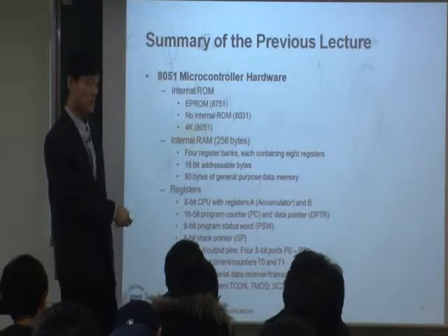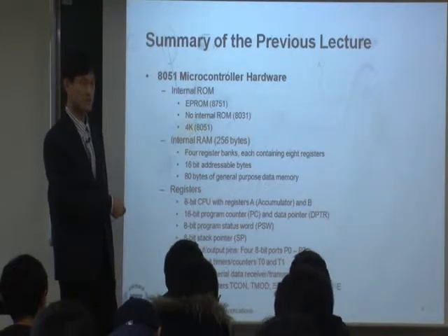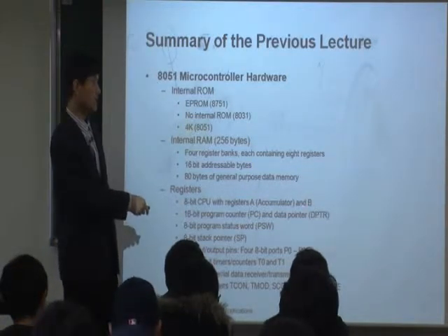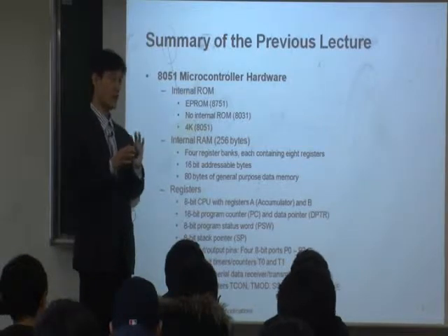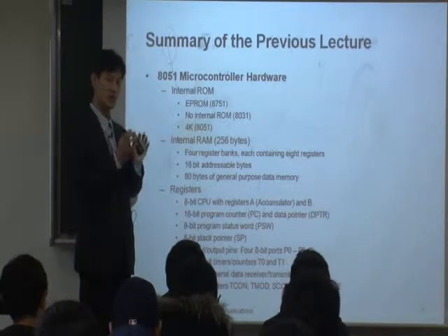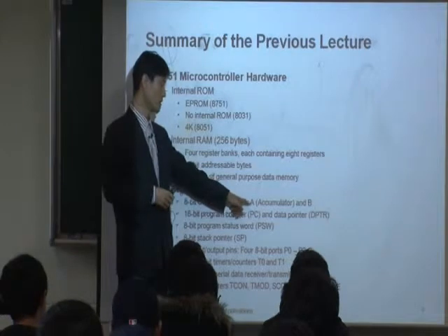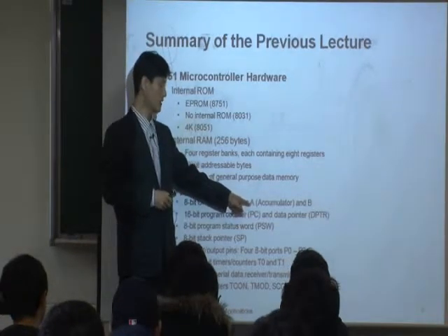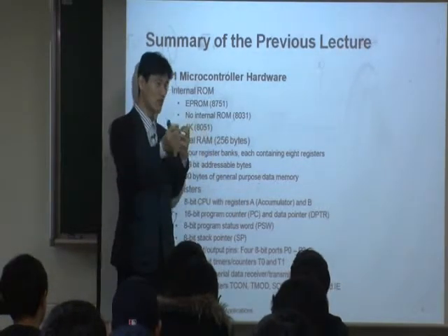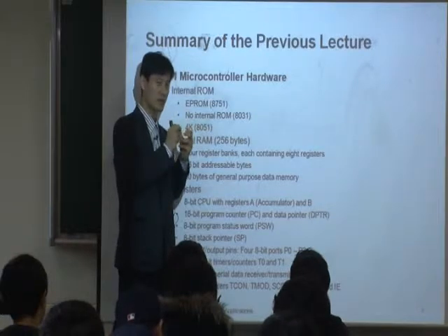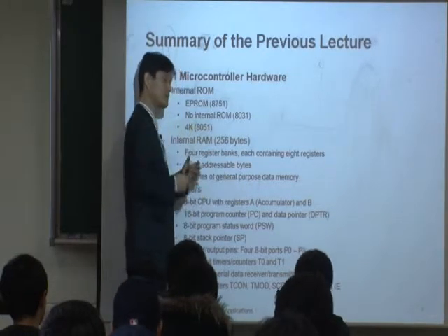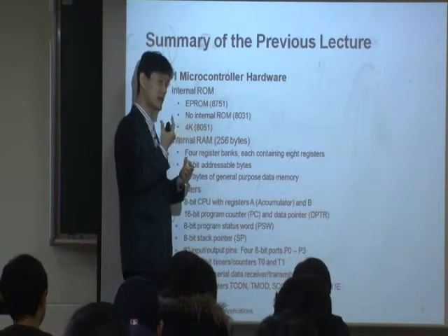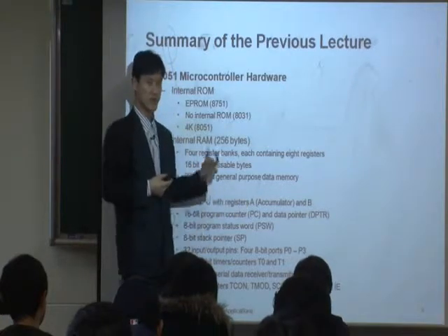All the registers pretty much are 8-bit size. Because here A and B, typically when you calculate like some addition or something, those values go into here. So this register A contains your value, data, okay? Data goes into A. So therefore your data typically is 8-bit, so therefore the register is 8-bit.